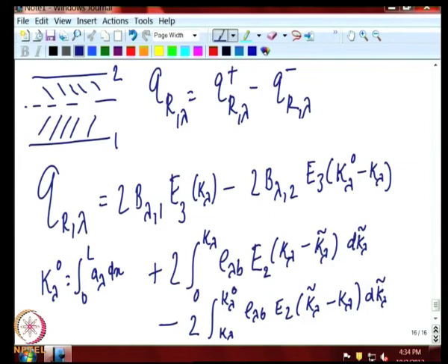So, this expression for radiative flux must be properly understood. The first term is emission from the photons leaving the surface 1 and on attenuation reaching the point of interest to us, and this attenuation term takes account of angular distribution of photons, or not all photons are coming vertically, some of them coming at an angle, and you are integrating all angles.